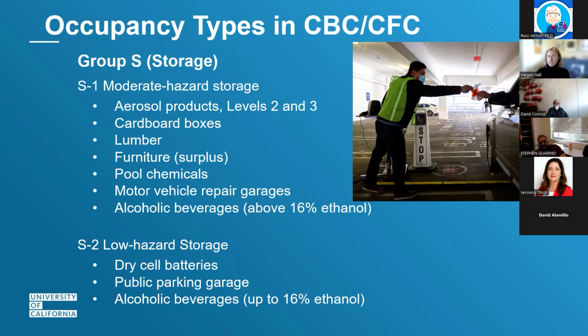It was designed as an S1, and it had the appropriate sprinkler coverage and spacing to store a fair number of class 3 oxidizers and things that were supporting the pool maintenance. So these are certainly present, and you can often have a lot higher MAQs in these spaces.